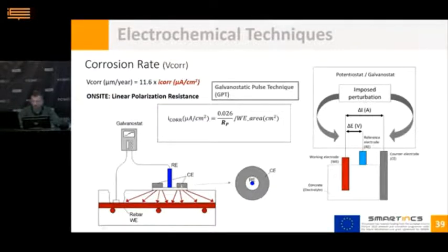The counter electrode should have a flat shape so that it can be easily supported. Normally, the counter electrode is a stainless steel disc or ring. In this way, the potentiostatic pulse method, described before, is applied, and the corrosion current density can be obtained simply.